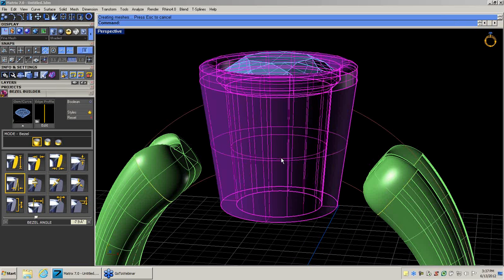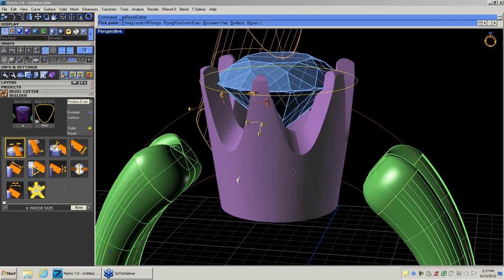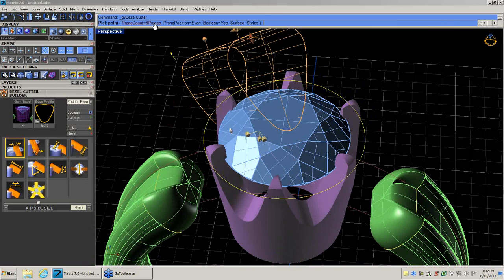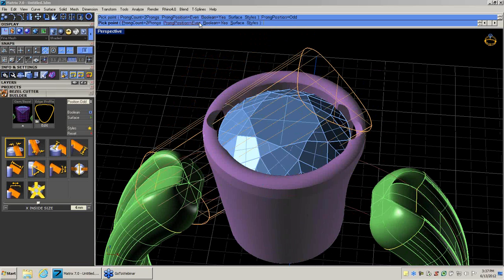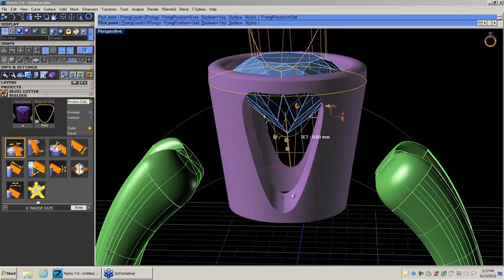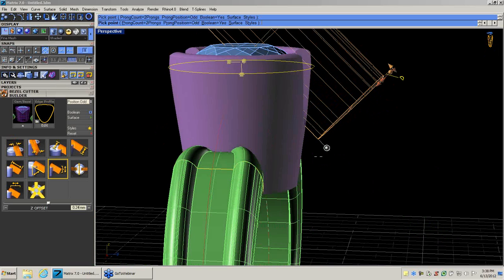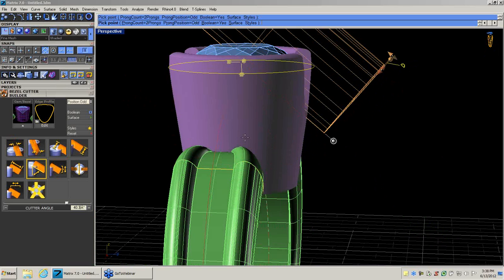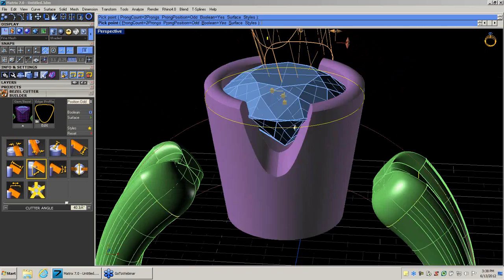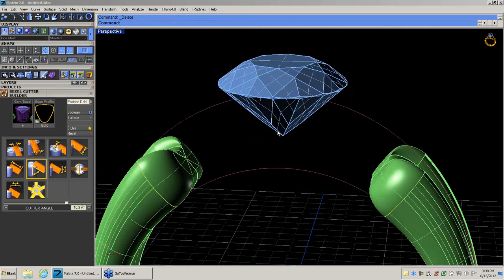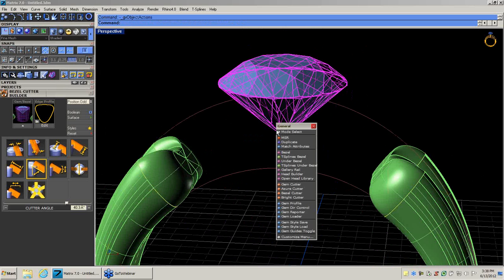I'll show you this tool real quick, but if I select the bezel and hit F6, I hit Bezel Cutter, it brings up a cutter that I can then turn this bezel into a head, and I can choose however many prongs I want, whether it's going to go this way or whether it's going to go this way. And again, knowing your jewelry and knowing how much metal we need underneath here to make this thing stable is critical if we're going to go in and do some sort of a half bezel. So understanding jewelry, once again, you have to know manufacturing.